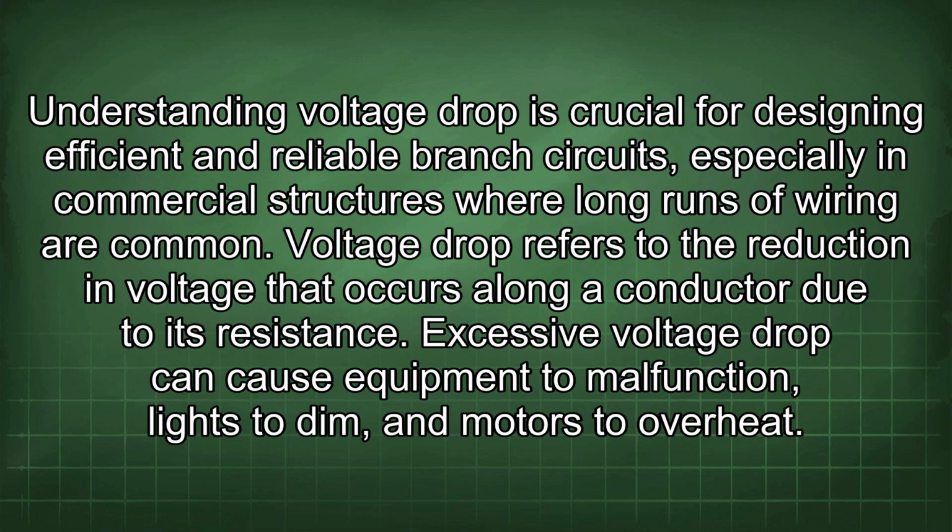Understanding voltage drop is crucial for designing efficient and reliable branch circuits, especially in commercial structures where long runs of wiring are common. Voltage drop refers to the reduction in voltage that occurs along a conductor due to its resistance. Excessive voltage drop can cause equipment to malfunction, lights to dim, and motors to overheat.